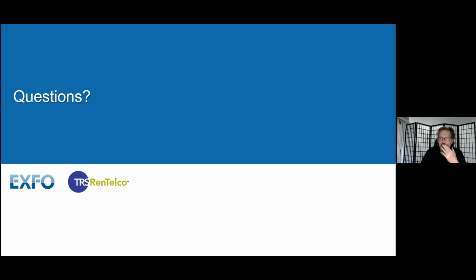The auto feature on the OTDR, we need to be careful with the auto feature. I probably should answer from the top down rather than the bottom up. Auto mode on OTDR, you have to be careful of, particularly in a DWDM network. Auto mode's great. In fact, I start with auto mode typically when I'm testing. So I'll get into the OTDR, I'll set it up for auto, and I'll let the OTDR narrow down.